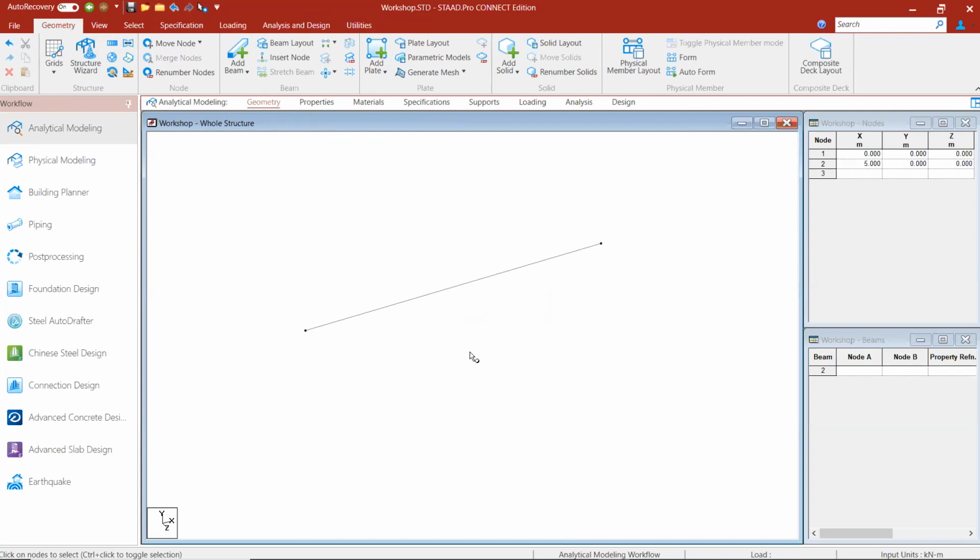So this is how you can find everything. In the beam section, you will have connect to x-axis, y, or z. If in any way you want to create a beam, or merge selected members, just drag your mouse and keep it on an icon, and it will show the details of that icon. Like renumbering beams, if you want to do that. Or if you want to break a beam, suppose I want to split this beam into two parts.